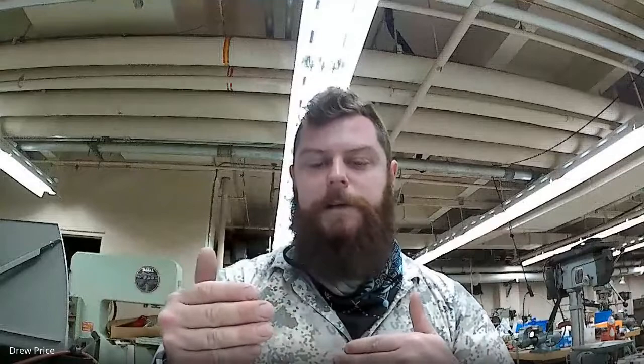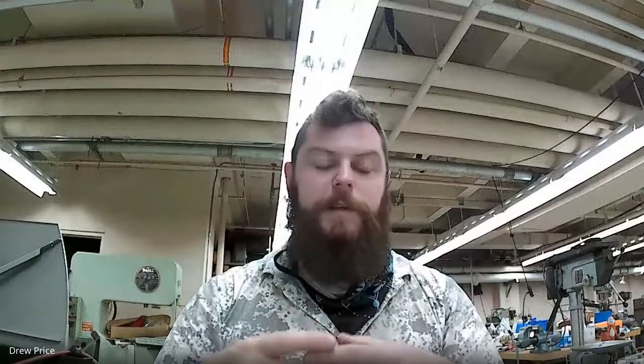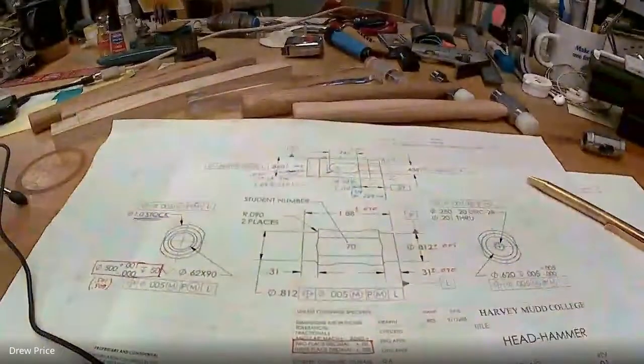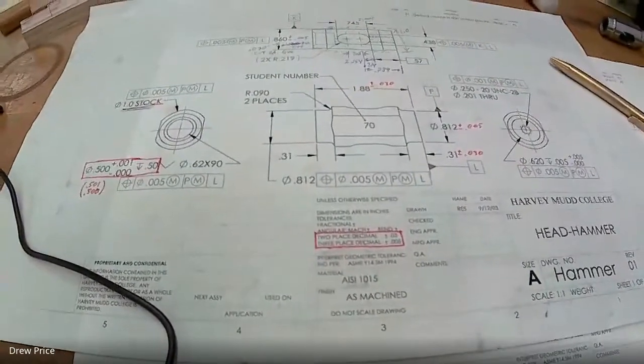How much parts of the process are worn will dictate the tolerance. If you've ever tried to cut something with a dull knife, it cuts very different than with a sharp knife. How rigid or floppy parts of the setup or the process are. Temperature can affect tolerances, and operators can affect tolerances. Different people can achieve different levels of precision using the same tools depending on their technique and experience and things like that. So I'm going to start looking at the drawings for the hammer that we would explore.